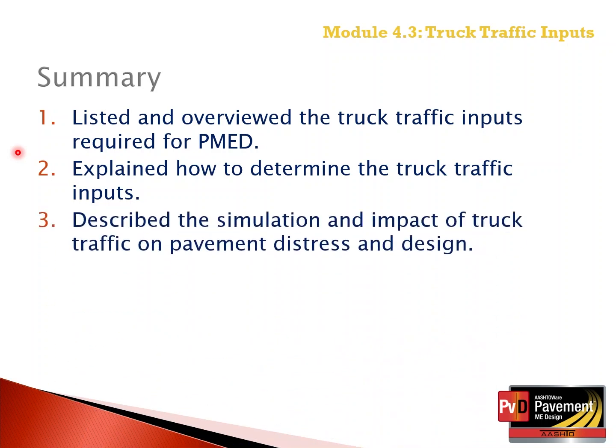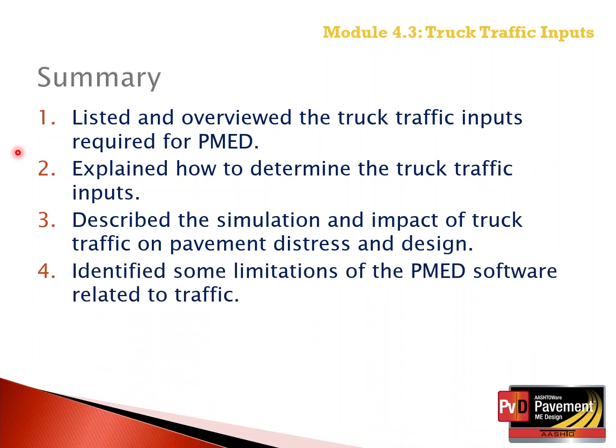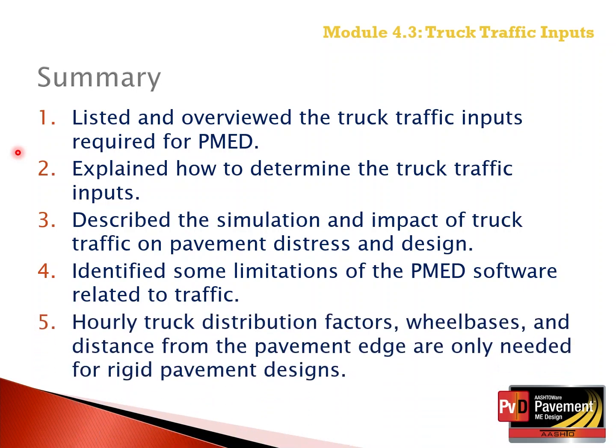We described the simulation and impact of truck traffic on pavement distress and design, especially looking at the axle weight distribution and the importance of overloaded trucks. We identified some limitations of the Pavement ME software related to truck traffic, and the hourly truck distribution factors, wheelbases, and distance from the truck edge are only needed for rigid pavement design.